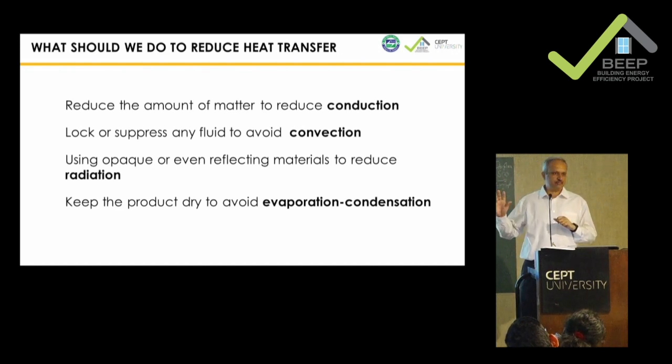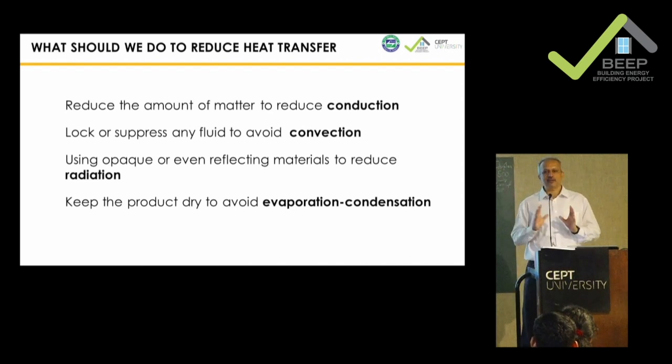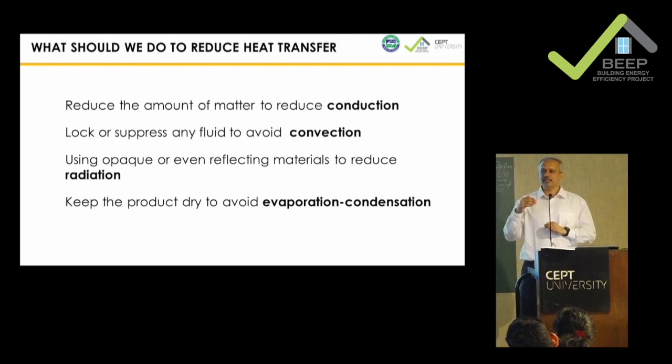It simply rejects. Versus if you start using a kumbal in the monsoon, it will take a while before your skin experiences water. This while depends upon the capacity of the kumbal to absorb water. And that is where thermal mass comes in. So thermal mass is like your kumbal, or rajai, and insulation is like your raincoat, which rejects right away. It doesn't allow it. It does absorb a little bit, but basically for heat, it rejects the heat.